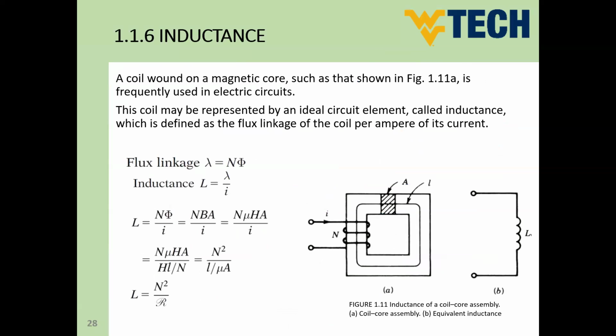One of the important things, guys, we have in magnetics is the inductance. You know that in electrical circuits, you used inductance and calculated the impedance and did the transient analysis, and you learned that the inductance is a storage element, so it can store energy. So how can the energy be stored? Actually, the energy will be stored by means of having an air gap in the core. So if you have an air gap in the core, this means you can store energy in this core inductance.